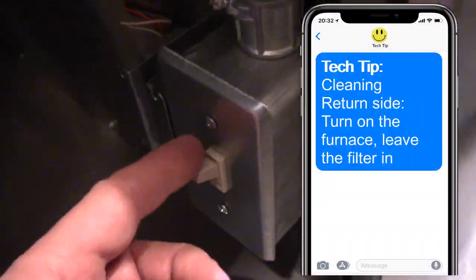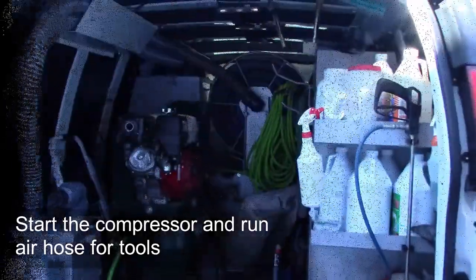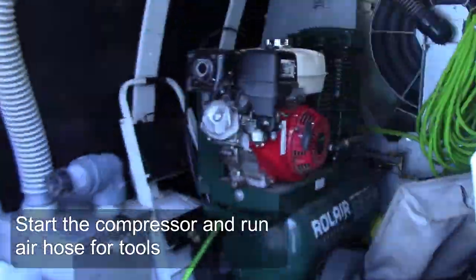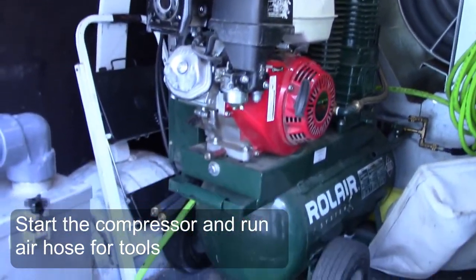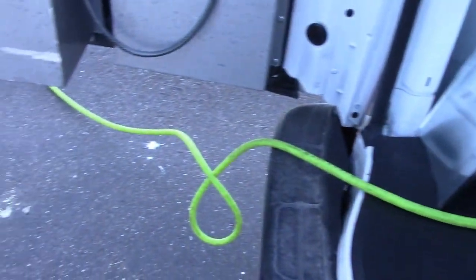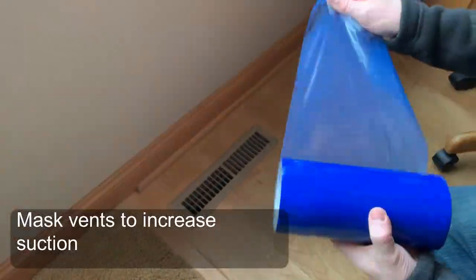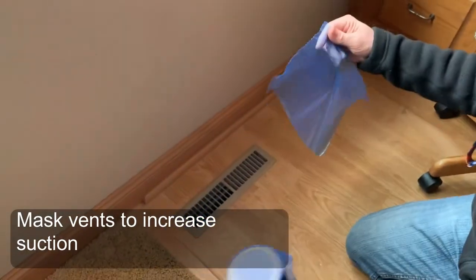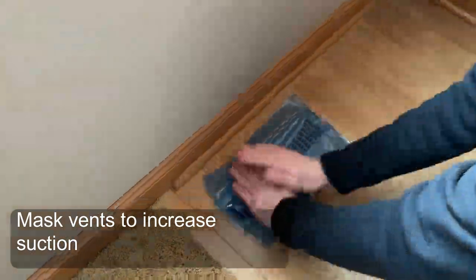Quick tech tip. Whenever possible, run the furnace fan when cleaning the return side to help move the dust towards the collector. Now start your compressor and run the air line to the furthest room from the furnace. Mask vents in many of the rooms to improve suction, especially in larger homes.